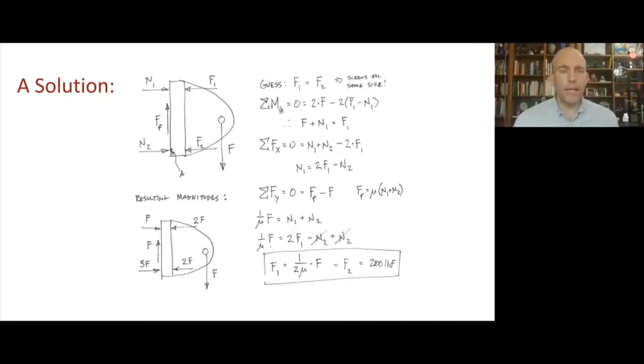And why am I characterizing the forces this way? So let's start with the screws. I'm saying that the screws provide just a normal force with no shear component. Why am I doing that? Because I would like to use these screws as they're intended, which is to be tightened so that they apply this axial force on the screw, rather than using them as shear pins. They're not designed for that, and it usually results in bending in the screw.